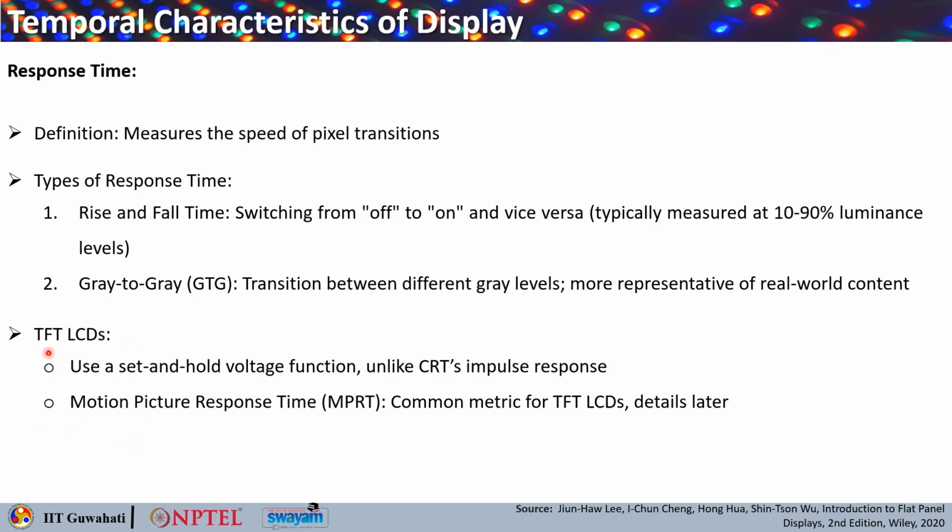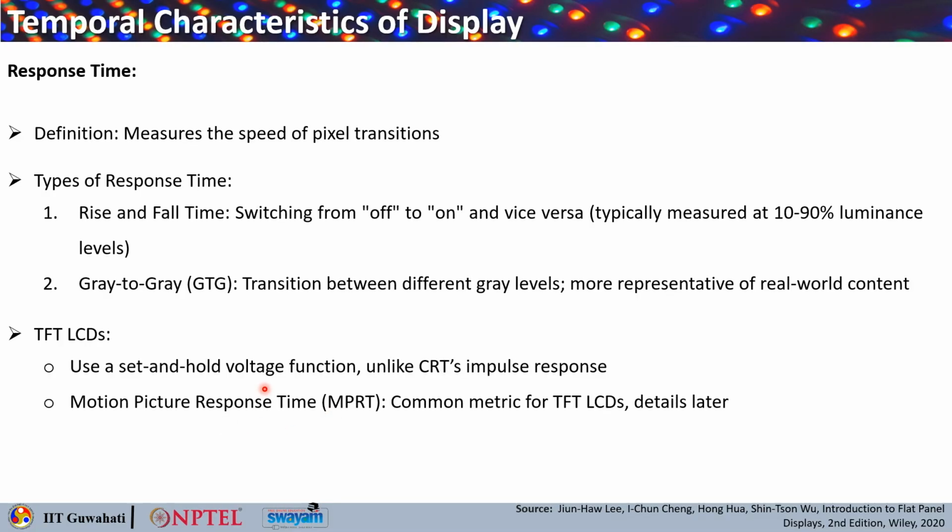When you think of LCDs, they are driven by TFTs, which are thin film transistors. There you need to use a set and hold voltage function to do this kind of response, unlike in CRTs where you have an impulse response. So here there is a finite rise time and fall time.